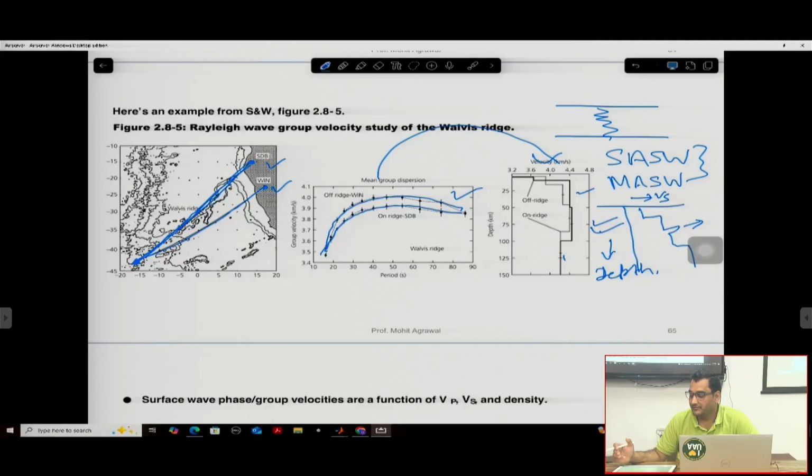Where you will basically be following the stress strain curve in order to find out the transfer function for the soil. Once you have the transfer function, you can easily compute how much of the energy available at the bedrock, in terms of ground motion, is transferring to the surface. So our aim is to find out how much ground motion is occurring at the surface of the earth where you are going to construct your buildings, right?